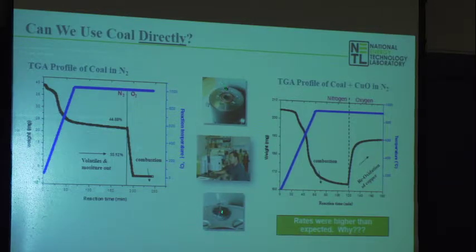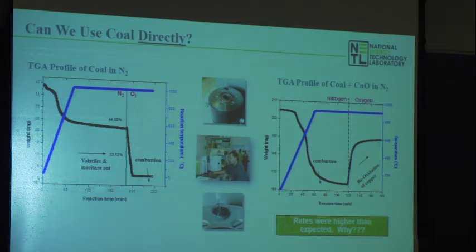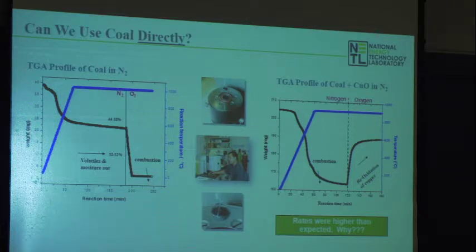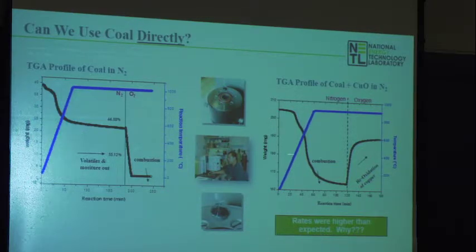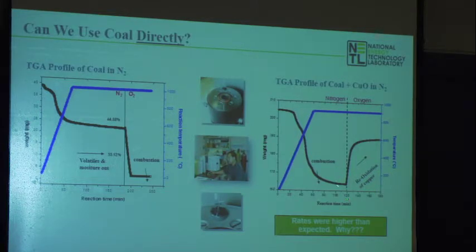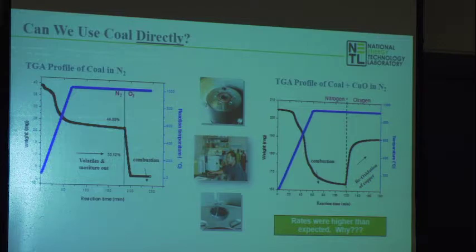Now I take the same pan, I load it up with coal as well as, in this case, a copper oxide carrier, and now nitrogen gas in the background. So there's no oxygen coming from the background gas. It is exactly the question that was raised just a few minutes ago. How do they react together on the pan? Well, you bring the temperature up, and now compare this black curve with the oxygen carrier to the one where I just have nitrogen on the pan. Boy, you see immediately I'm consuming pretty much everything, right? With no oxygen in the environment around, I'm down to that same level. So clearly I'm getting the oxygen out of the oxygen carrier. And I consumed all the carbon and hydrogen that was in the fuel.